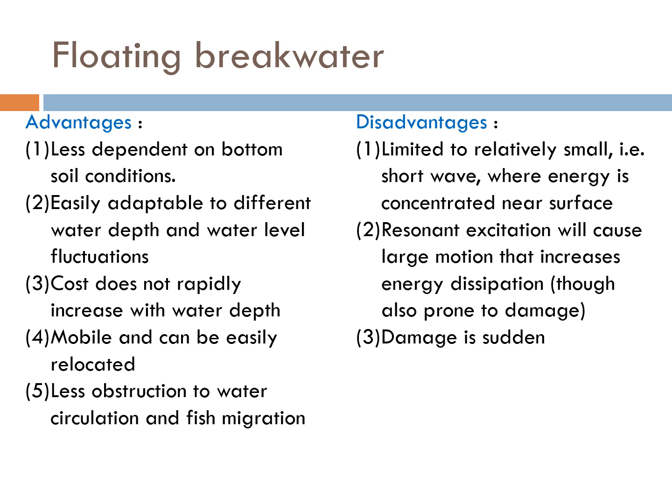Floating breakwater can also be designed to be mobile so that it is only deployed when needed and can be easily relocated. But perhaps the most important advantage of a floating breakwater is that it allows the free passage of current as well as fishes in the gap below, so that it imposes least environmental damage to the local surrounding.